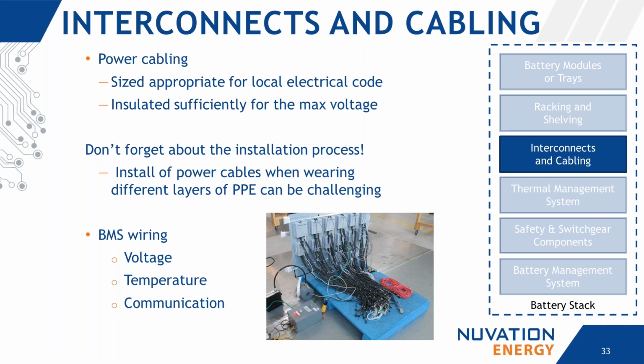When dealing with high voltage connections, PPE such as arc flash suits and insulated gloves are typically required. If you've never worn one of these suits before, you may not be aware of how much dexterity is lost when wearing one. It's so important to ensure that the procedure for installing power cables is doable even when limited by the PPE that's required to be worn.